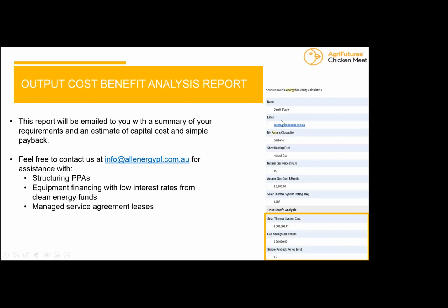Here's an example that I just ran on offsetting natural gas with solar thermal. And I mean, the really critical stuff here is what's your CapEx, so that's your system cost, how much you're saving, and an approximate simple payback period. You will be able to get more detailed analyses if you go to the market, or for detailed site-specific modelling. And as per any good procurement approach, get 3 complying submissions from the market before making a final decision. But certainly these tools give you a good guide on where some opportunities might lie.